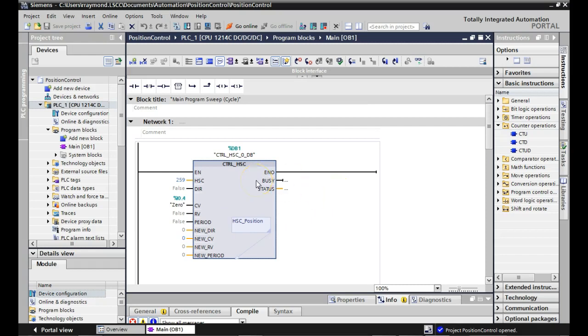What else? That's basically it that we're going to use. This is an error right here. This guy is true anytime there is no error, and it's false when there is an error. This tells us when it's busy. So on the 500, this would be timer timing, right? You understand? And this would give us the status. This would tell us if there's any problem. Are we okay?